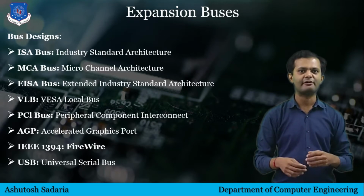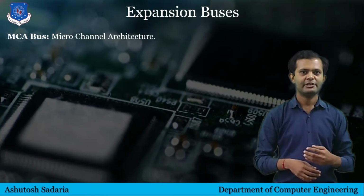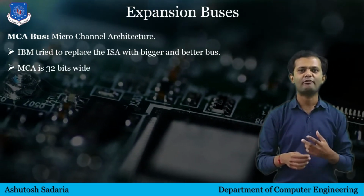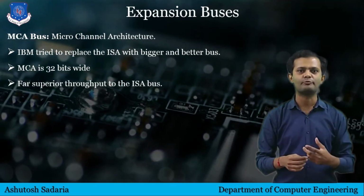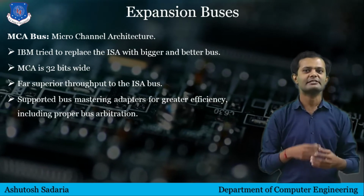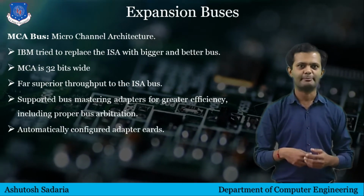So the ISA bus we covered in the first video. The second bus is the MCA bus. The full form of MCA bus is Micro-Channel Architecture bus. Using this, IBM attempted to replace the ISA bus with something bigger and better. MCA is 32-bit wide and offers several significant improvements over the ISA bus. It had far superior throughput to the ISA bus. The MCA bus supported bus mastering adapters for greater efficiency, including proper bus arbitration. MCA automatically configured adapter cards, so there was no need to mess with jumpers.